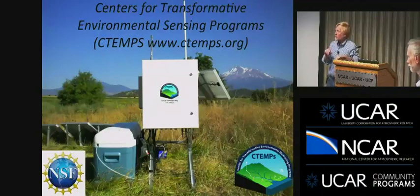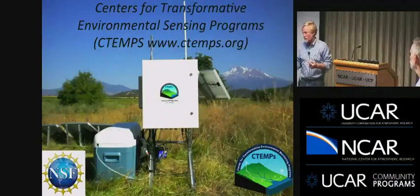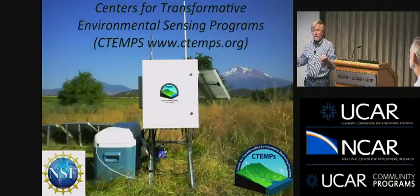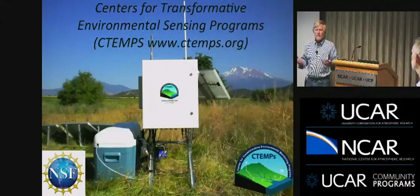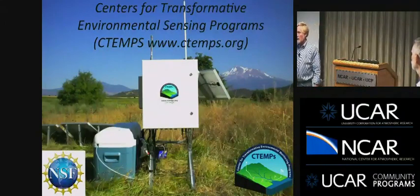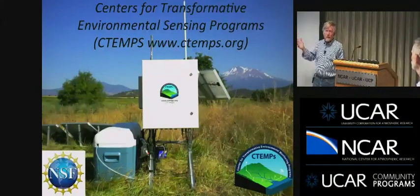One is, let's think of the thermal mass and the ability to change temperature. The nice thing is that the heat fluxes are all radial in the cable, so they are relatively short distances. But some of the big cables that I've sent around to you will certainly have a time constant of somewhere 30 seconds, 2 minutes, something like that. So there's no question that if you wanted high frequency, temporal frequency measurements, you're going to filter out probably up to 30 second, 60 second stuff.